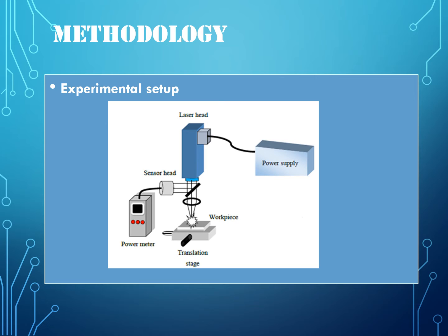The pumping voltage is varied from 500 volt until 1000 volt from the control panel on the power supply unit. The laser output energy is varied up to 600 millijoule, measured with an Ophir Orion PE, Ophir PE50SH detector. The laser was focused using a lens of 100 millimeter focal length to achieve enough energy density for the roughening process.